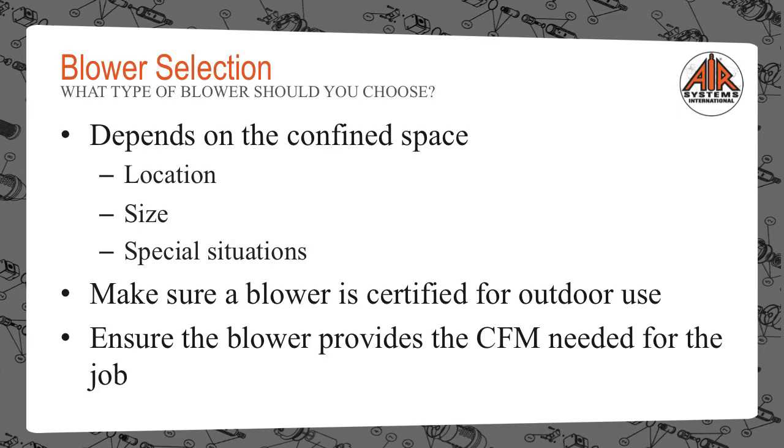The first thing to consider is, is the blower certified for its intended use? For example, if it's going to be used outdoors, is it approved for outdoor use? Surprisingly, not all blowers are. The next thing to understand is how to evaluate a blower. Pay attention to the CFM, cubic feet per minute specifications after ducting is attached to the blower, not free air delivery.